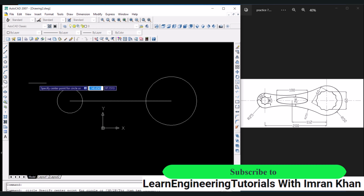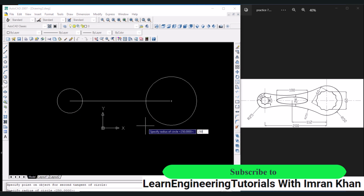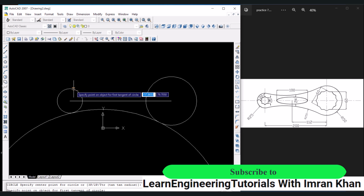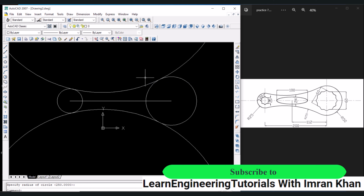So for that we can go to the draw command and then select TTR or tangent radius option, or we can just click on the circle icon. Here we can see the TTR option, which can be activated by typing T, enter. Now we will select this circle, similarly this circle, and we will write the value of the radius as 250, enter. Press enter again, press T and press enter. Click on this side of the circle, this side of the circle, and 250 is already selected, so press enter.